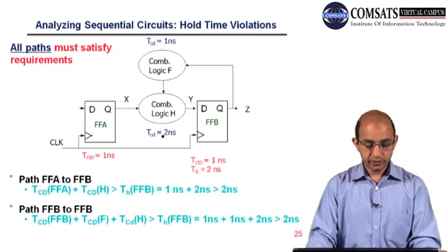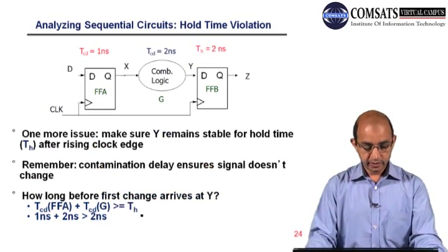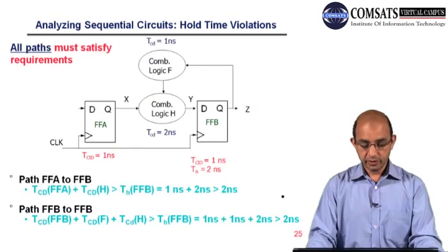The contamination delay should be greater than 2 nanoseconds so that we can meet the hold time.